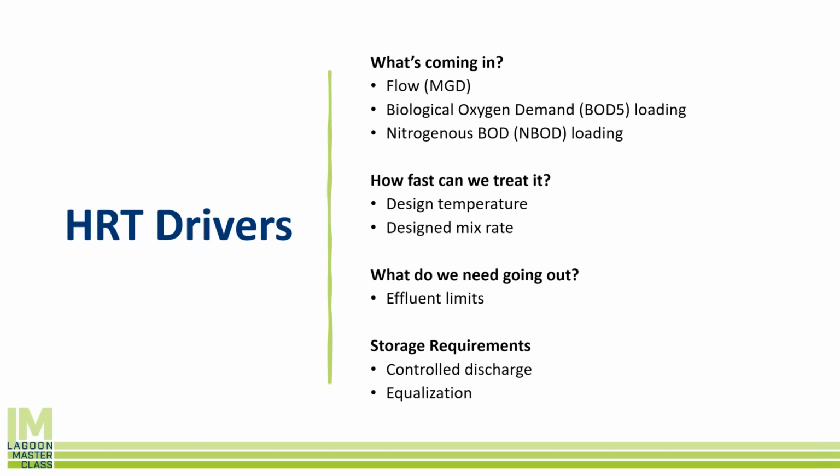Also, we can augment the kinetic rate. So if that K that I discussed earlier, we can increase that K rate by increasing the mixing we put in the lagoon system. If we get the bacteria, the waste, and the air more in contact with each other, we can get them to eat the waste faster than a typical partially mixed lagoon system would do. Point being, if we increase the mix rate, we can decrease the HRT, or how long we need to hold on to the water, because we're eating it at a faster rate.